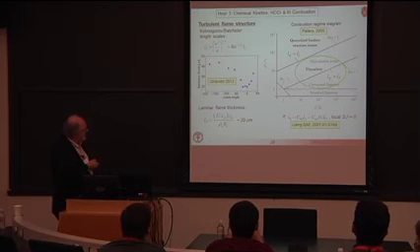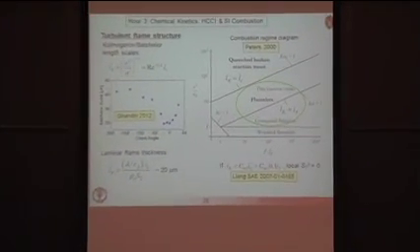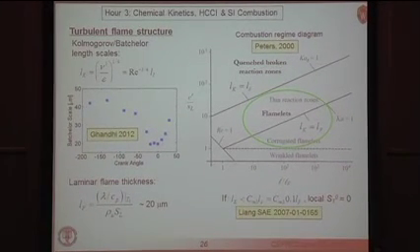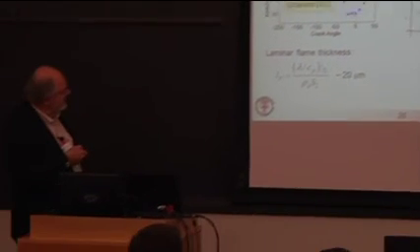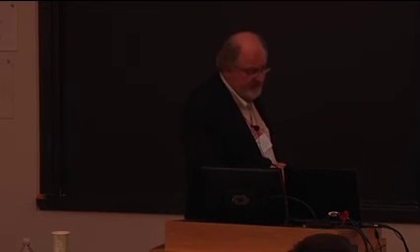So Professor Gandhi in our group has developed some really amazing measurement capabilities, and recently made some measurements of the Kolmogorov scale of turbulence in an operating engine as a function of crank angle. And what he found was that the smallest scales of turbulence are reached around top dead center and are also about 20 microns in thickness. So basically, the smallest scales of turbulence are already bigger than or comparable to the flame thickness, which is, I think, very interesting. But it has another very important consequence.